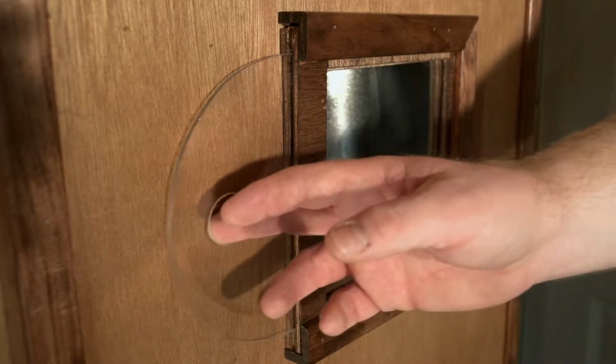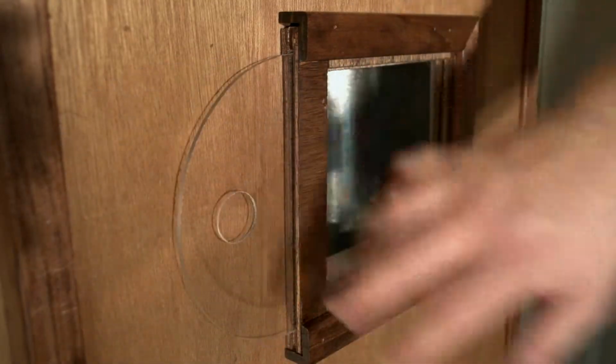Here we see a very common thing. This represents a chaseway from attic to crawl space. It may contain ductwork, it may contain plumbing penetrations, but the problem is this is usually unsealed at the top and bottom where these penetrations enter the envelope, and they can be very large holes frequently. So we have air coming into here, which then comes into the interior of our house. Often through things like this would represent an unsealed chimney entry. Often these fireplaces are removed and the chimney is left. So we want to make sure those are sealed.